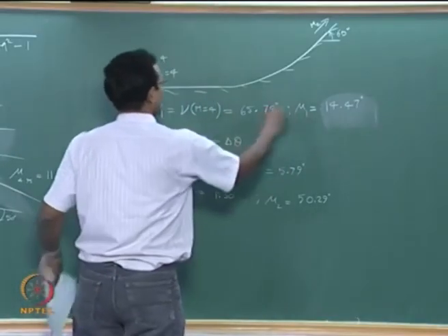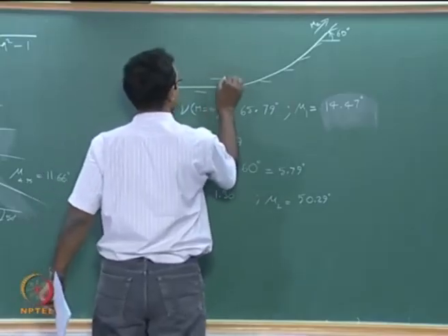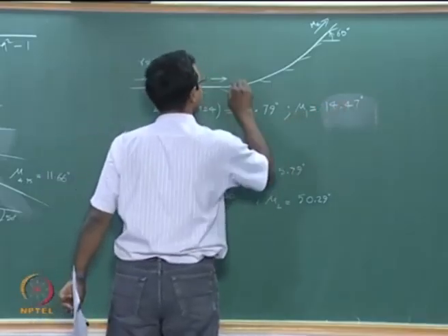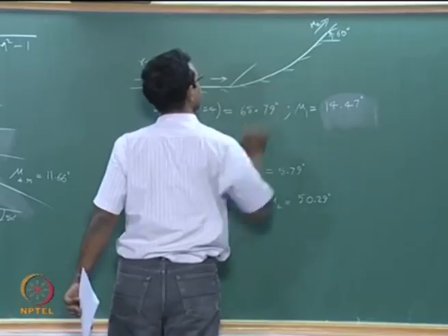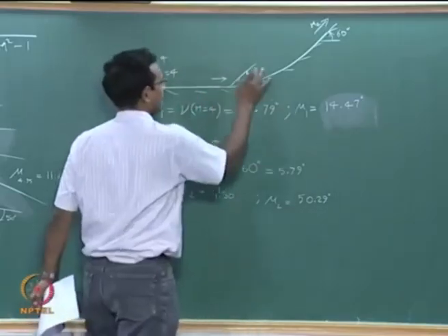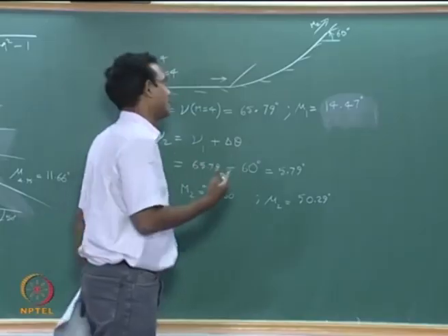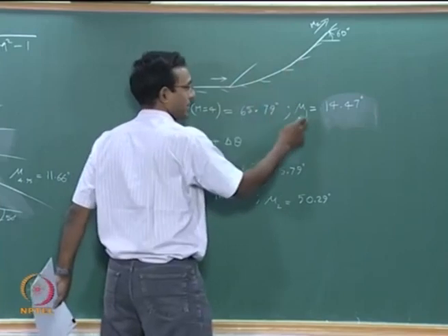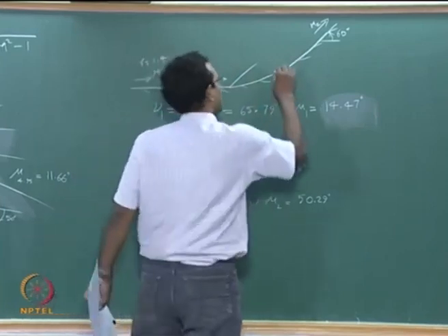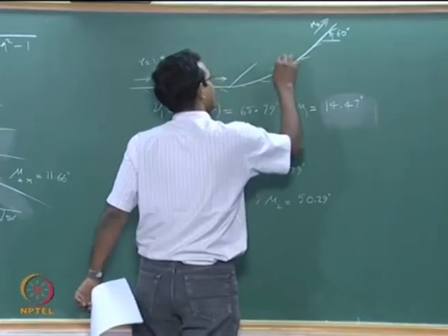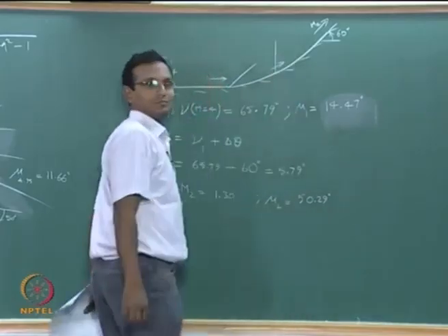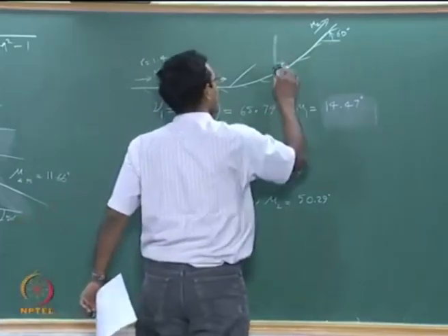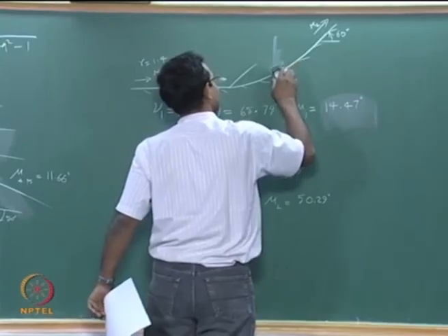Okay. So what I am seeing is locally with respect to this flow vector, Mach 4 flow has a Mach angle 14.47, which is a very small angle, subtending an angle very small with respect to this. I am actually drawing it slightly big so that it is easy to visualize. Okay. And then as it goes, Mach number decreases, which means my mu angle should increase. So when I am drawing my local velocity vector like this, with respect to that my mu would have increased. Okay. I am drawing too high probably here.